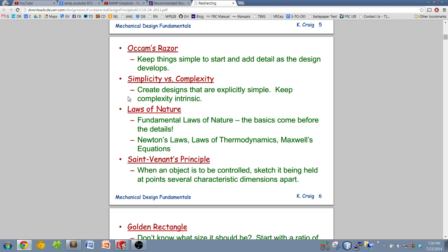So a lot of your design has to be learning the principles of what will actually work, CADing it, making sure it all fits right, making sure it's actually buildable. A lot of little things that people miss that makes robots really complicated is if you design something where it's impossible to get that bolt in because of how you made it. There's some other face next to it, or you can't unscrew something to be able to take a motor out. When you have to go through whole seasons like that, they get really annoying.